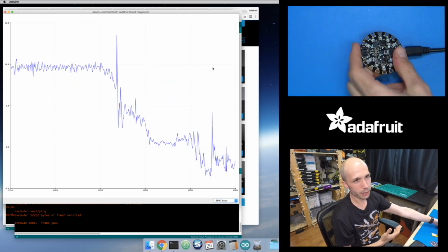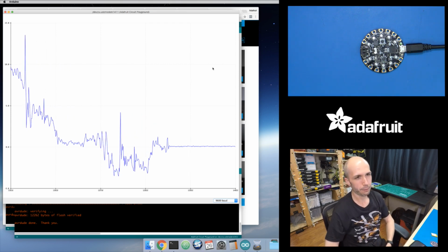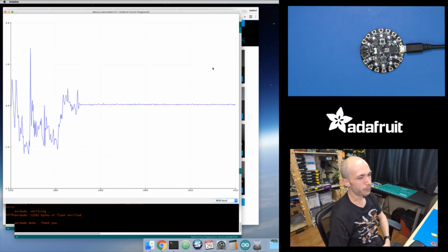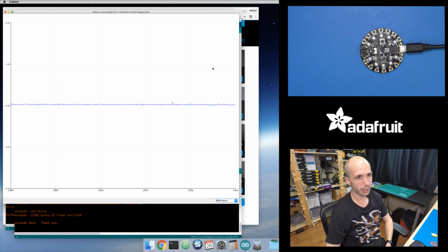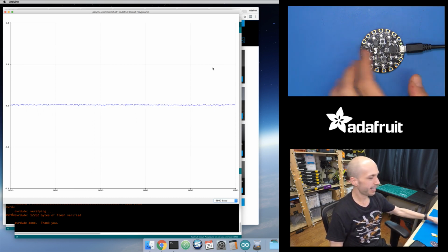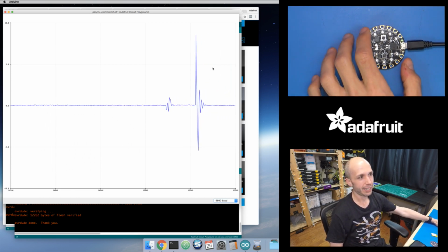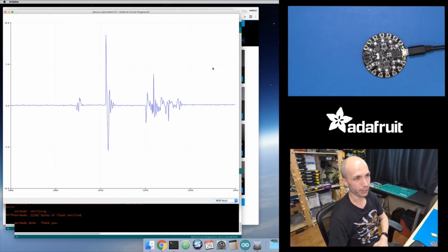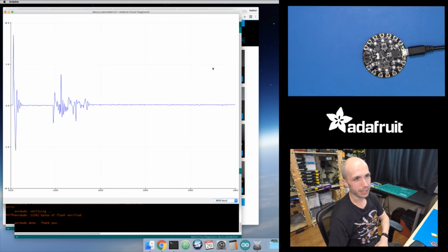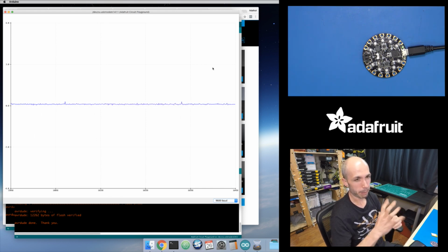So that's where that window or threshold peak detection falls down, because if you don't have control over what the steady state values are, or if that steady state value changes, it gets more difficult. You can't necessarily detect that peak with that simple logic. That simple approach definitely works though, and it might be the first option to think about, but you might run into trickier cases like this where you need to filter out some of that noise or account for the fact that there's a steady state and then a big change from that steady state is what I want to look for.